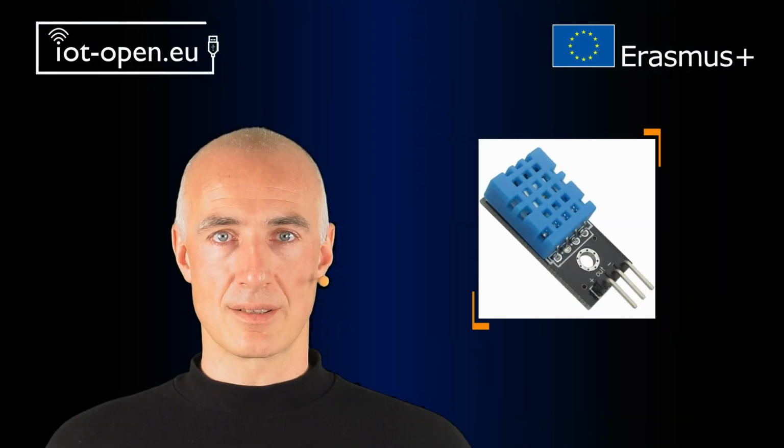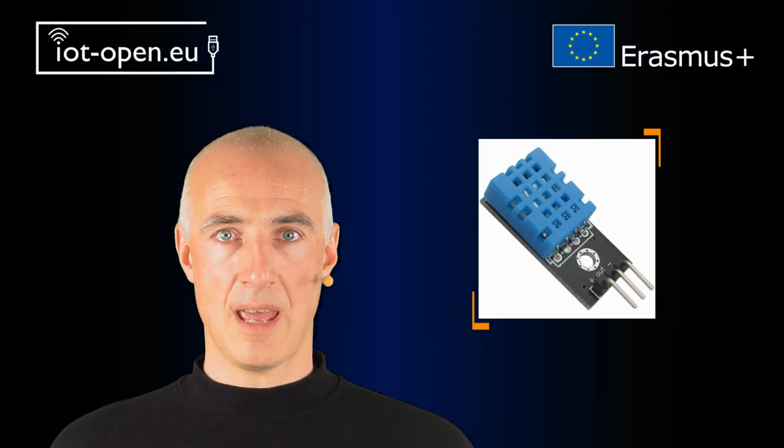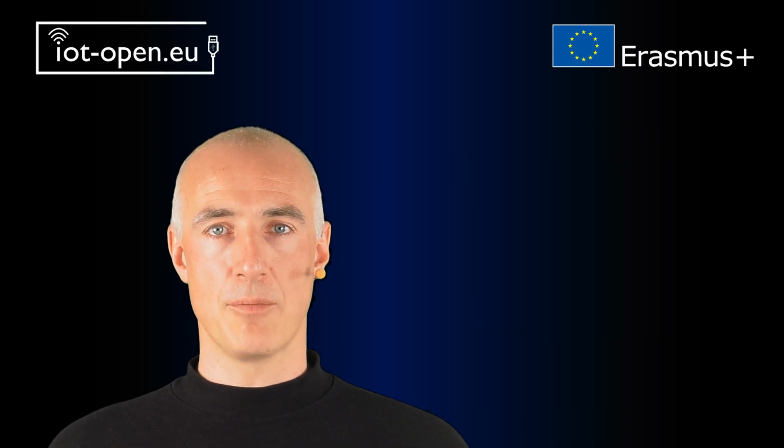A humidity sensor is a sensor which detects the amount of water or water vapor in the environment. The most common principle of the air humidity sensor is the change of capacitance or resistance of materials which absorb moisture from the environment. Soil humidity sensors measure the resistance between two electrodes. The resistance between electrodes is influenced by soluble salts and the amount of water in the soil.